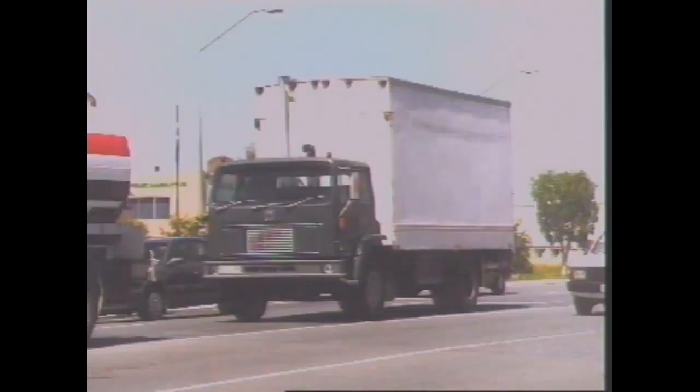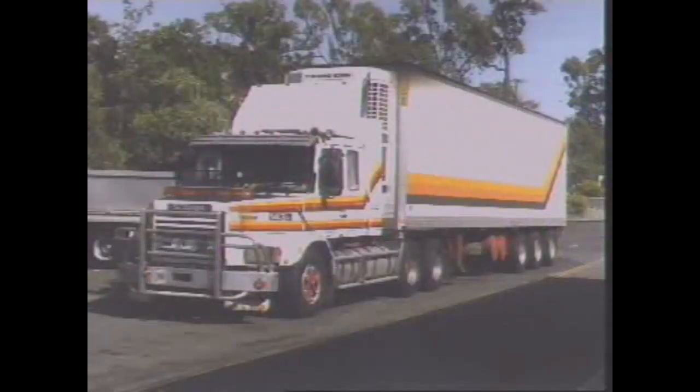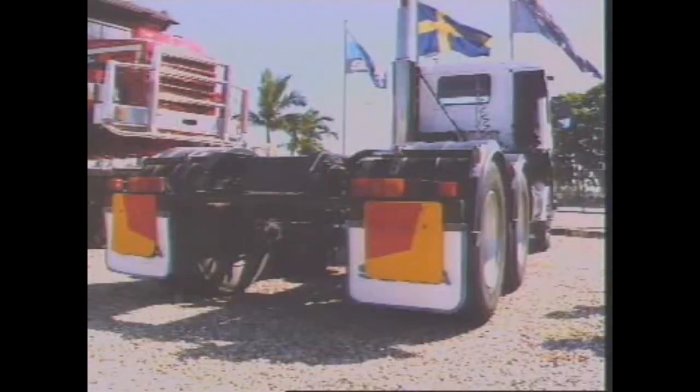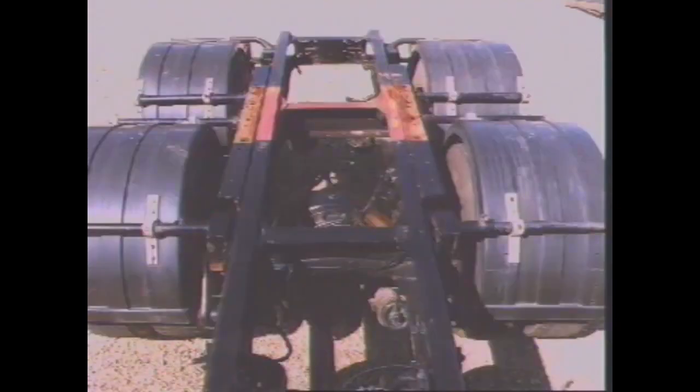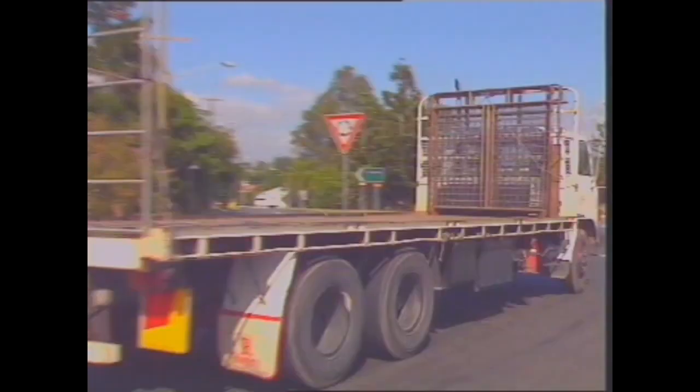On commercial vehicles, the load carried on a single axle is limited by law, so vehicles with extra axles are common. This layout has 6 wheels to support the vehicle, but only 2 drive it. The extra axle at the rear is only used to support the weight of the vehicle. This extra axle is sometimes called a lazy axle. This is called a 6x2 vehicle.